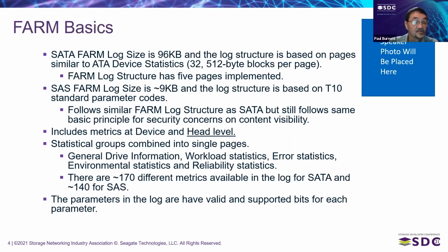The log includes metrics at device and at the head level. In many of the standards now, they have terminology for elements, which is basically a head. So this log has by-head metrics, which actually provides better insight on HDD areas, since it's very head-centric about usually where the failure modes occur.